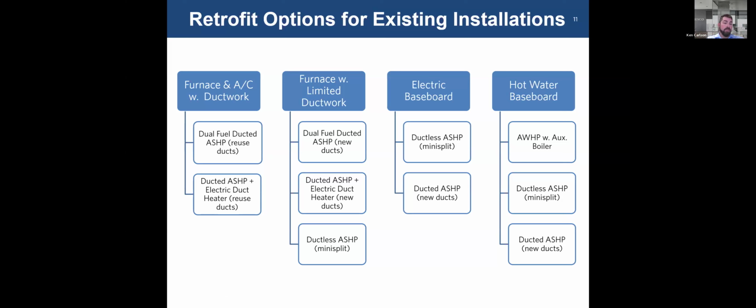If you want to get off natural gas and fossil fuel altogether for whatever reason, you can go to a ducted air source heat pump with electric duct heaters as the second stage. In this situation, you almost guarantee that you're going to need electrical resistive heat on top of the heat pump. The heat pump capacity is going to be limited, one in part by heat pumps in general, and two by the ductwork. So you'll need that resistive heating to increase the temperature of the discharge of the unit to satisfy the heat load of the building.